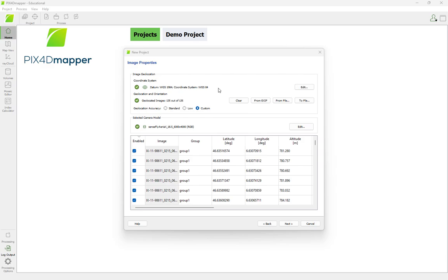For most drone imagery, the WGS84 horizontal coordinate reference system is automatically encoded in the image's metadata. If you capture your images with an RTK or PPK equipped drone or mobile device, the image coordinate reference system corresponds to the CRS used to receive the GNSS correction data.